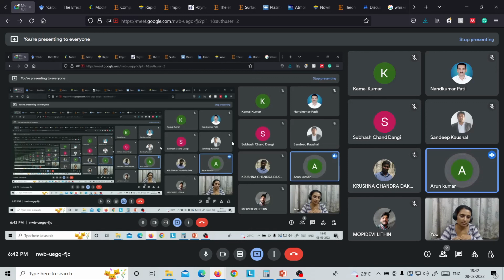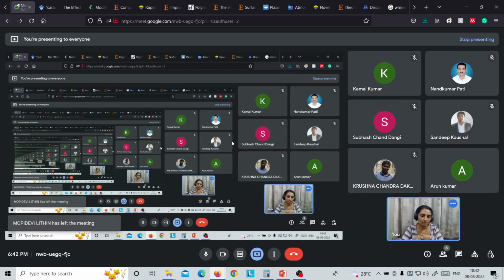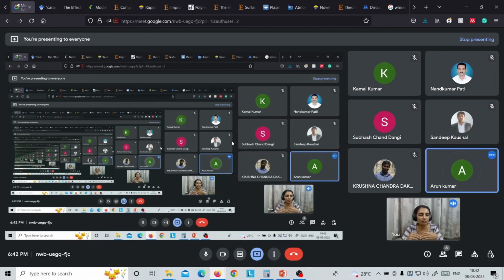What is the specimen size, madam, usually used for testing? It's a cube of the size 5 mm. 5 mm, 5 mm. And it needs to be conditioned. So moisture is removed for around 2 days, then it's kept in a desiccator, and only after that it is coated with a gold layer, which is known as gold sputtering, and after that we place it into that machine. So we'll obtain this contrast as per our requirements.